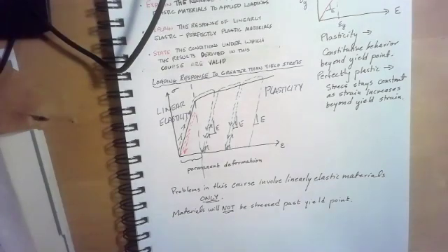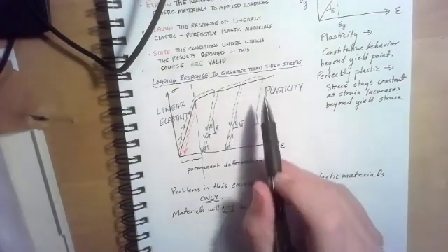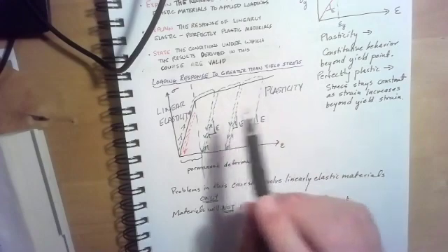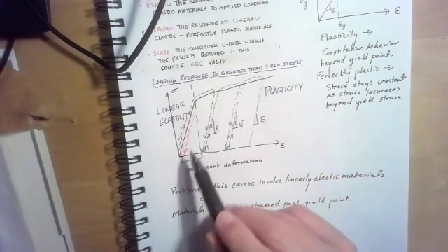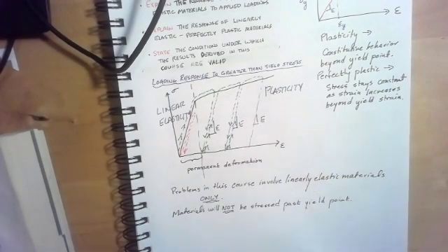And by the end of that drawing process, you might come out with a yield stress of somewhere around 70 KSI. So you would get a higher yield stress in materials by going through this drawing process and subjecting the materials to some permanent deformation and some strain hardening.